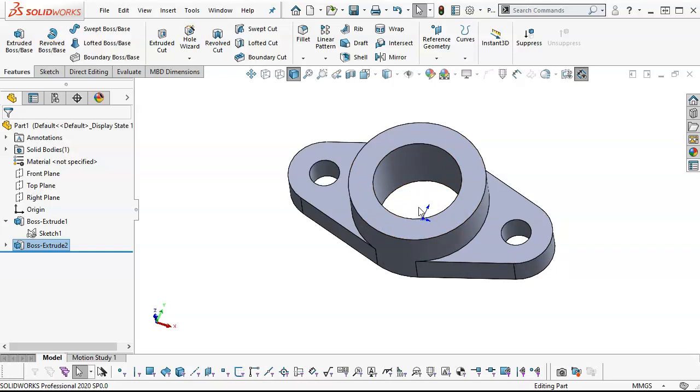From a CNC standpoint, I almost want to keep those because another radius is going to bring this up as an additional function, and I'm not going to be able to bring it tight right back to that corner anyway. One of the radiuses I could put in, if this is a stress riser, if it needs the extra load, I could put in the 3mm fillet at the base, and I could get that in there pretty easily with the machining process.